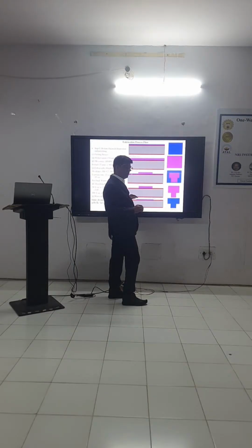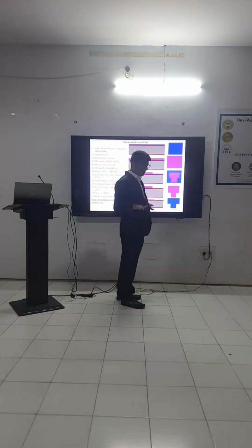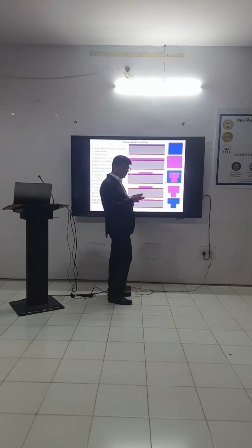For that I will use sputtering. With the help of sputtering, I do not require any lithography because I want this mirror layer throughout the wafer, because this mirror will work for all devices, the same mirror. Clear? So for that I do not require any lithography. So first I will deposit my molybdenum layer, and over the molybdenum layer I will deposit my SiO2 layer. Like that I will deposit three mirror layers one by one.